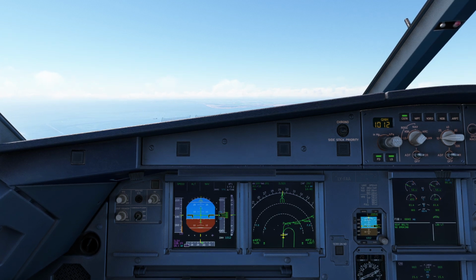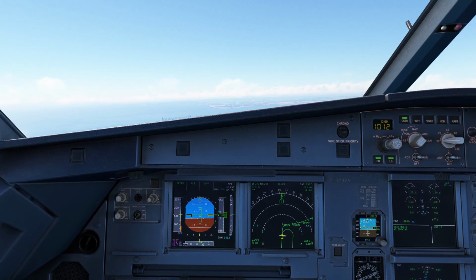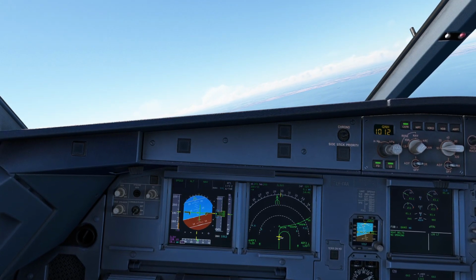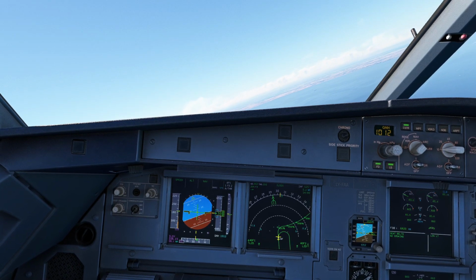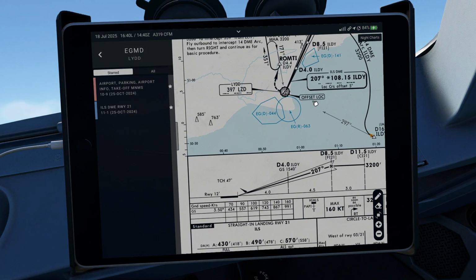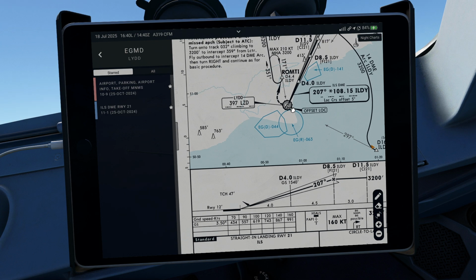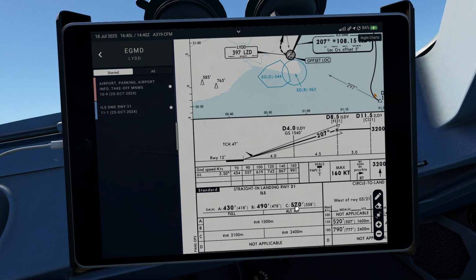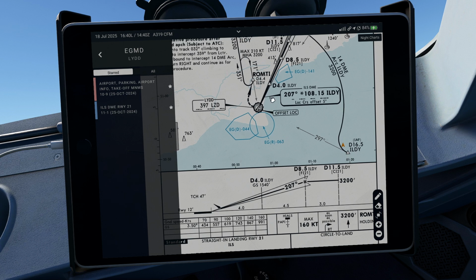But here are some operational considerations today for us on board the Airbus A319. According to recommendation, and also the nature of the approach, which is almost 5 degrees offset, we should maintain at the last stage just above the minimum or decision altitude of 570 feet, keeping the runway visual and turning left to align with the runway center line.